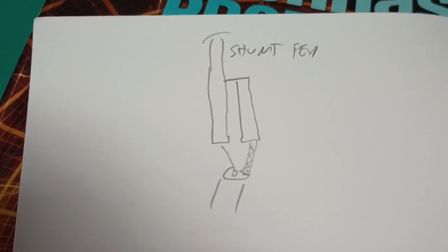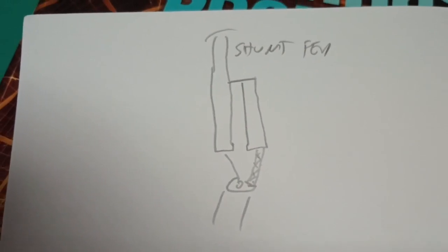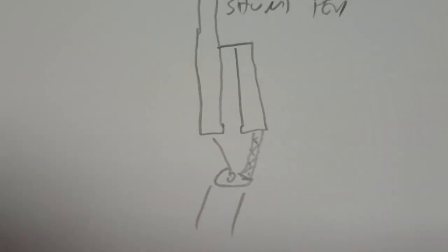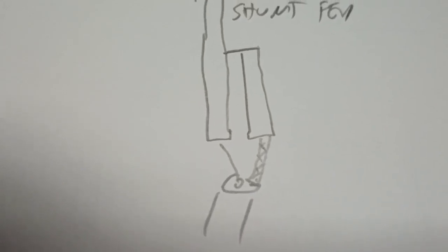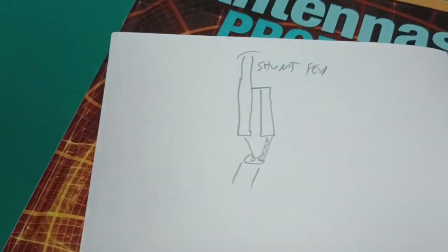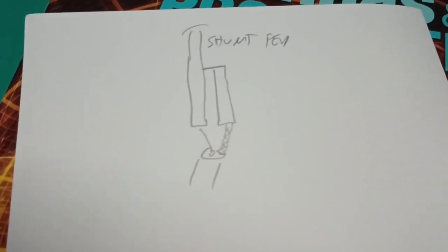Now, a modification of that, which incorporates the idea of a magnetic loop and a vertical monopole, is what's called shunt feeding. That combines a magnetic loop, which is the right side tube, which is the shunt, connecting at the top, going over and coming back down the antenna tube. That's a magnetic loop. And it is coupled into that vertical radiator. Just that is not an antenna. A loop is not an antenna. A loop is a single turn inductor.